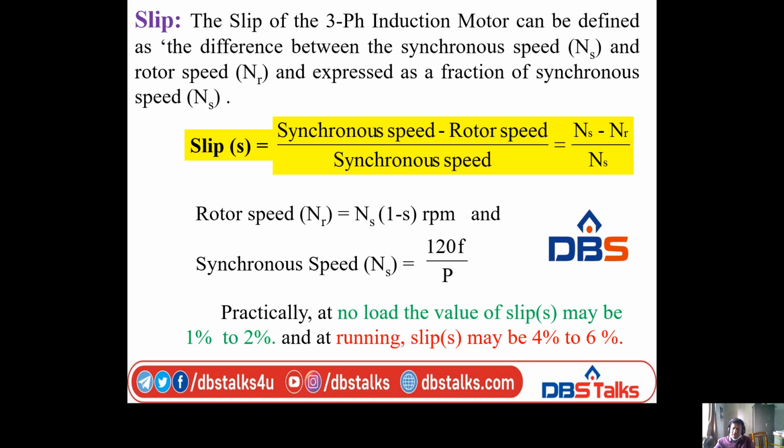For a three-phase generator it will be different, and for the braking condition it will also be different. For the three-phase induction motor, slip ranges from 0 to 1. Zero corresponds to the ideal no load condition, and 1 corresponds to the starting condition.